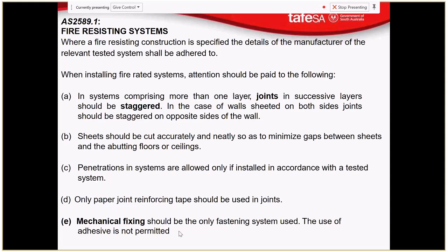Mechanical fixing should be the only fastening system used. The use of adhesive is not permitted, and that's for the same reason: mechanical fixings under heat are still going to stay fixed, whereas liquid nails, for example, you heat that up, it may go soft and separate.